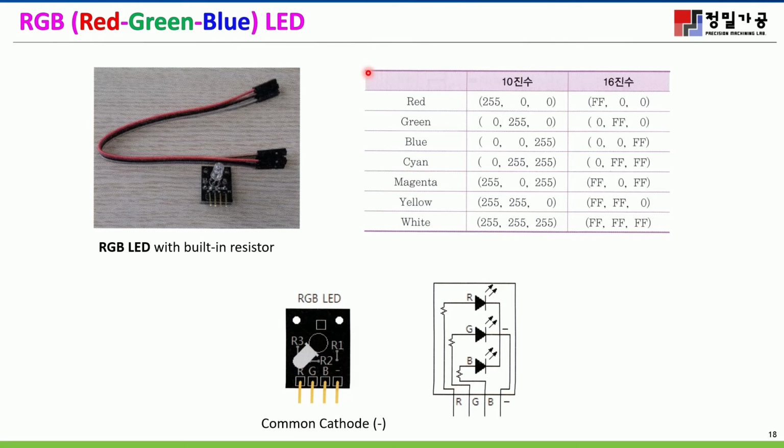To generate a color, you just activate, for example, red by giving the PWM value 255, the maximum. Because this is red, green, blue, the green pin is in the middle and red is the first pin. So activate 255 first for red, green in the middle, and blue for the last.